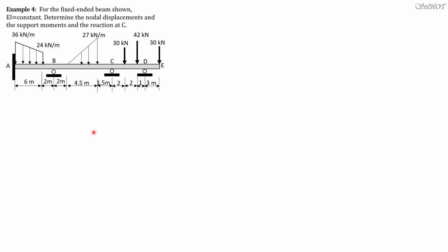First, let's have a strip. So for this load AB here, if we denote x as the distance of the centroid of strip from the 24 kilonewton load, and we imagine that we have two loadings, rectangular and triangular.